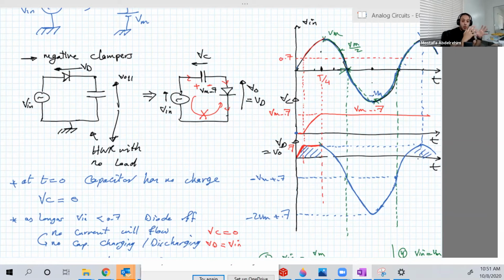So as I said, we level shifted this input signal down by minus Vmax plus 0.7. If we ignore the plus 0.7 compared to the minus Vmax, then we level shifted this signal by minus Vmax, just as our requirement, which is adding some level shift to the input signal.